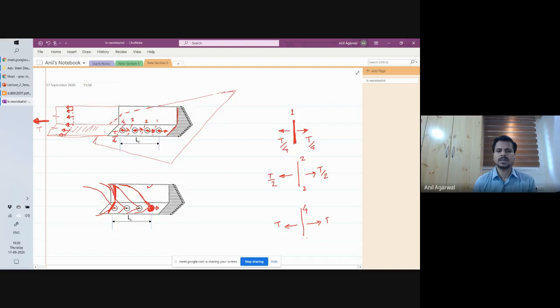Generally, the rule of thumb is that if you have a lateral dimension of D, then by 2D length, you distribute the loads uniformly, or the boundary effect goes away. That is just a rule of thumb. So by a certain distance, the other leg must have been loaded with these stresses decently, right? So this would have worked. Even some of the stresses from the second bolt would have been transferred to the second leg. But the forces that were transferred from the last bolt are still completely on this leg only. And only a very small portion of the third bolt would be there.